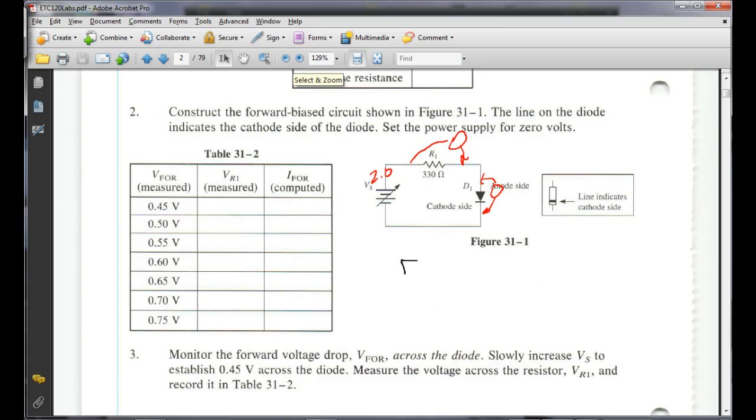And we're going to have to do that several times in this lab, guys. I mean, in this book, because they're depending on power supplies and signal generators and stuff that we can adjust down to 0. One of the labs says we want like 10 millivolts out of your function generator. I've never seen a function generator that you can adjust down to 10 millivolts. So it's no big deal. Well, let's do one. We'll just use a pot.